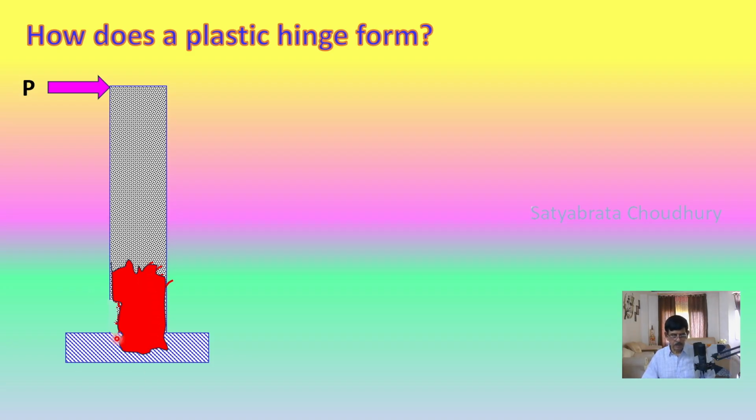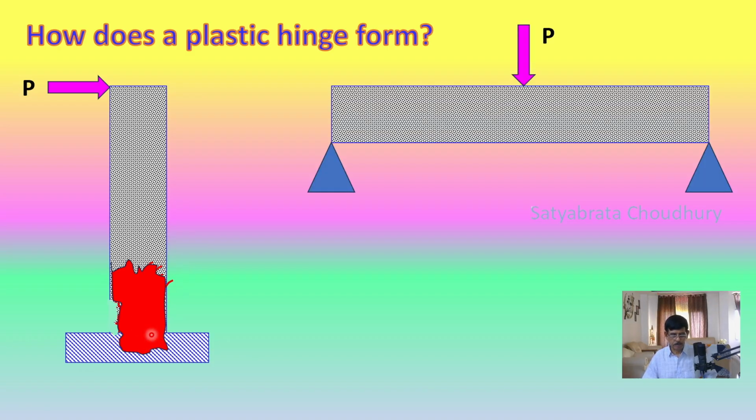A part of the hinge may go inside the support, which is called strain penetration. So it is a definite length here, but for simplicity in different software like SAP 2000 and ETABS, it can be considered as a single point, which is called lumped plasticity.